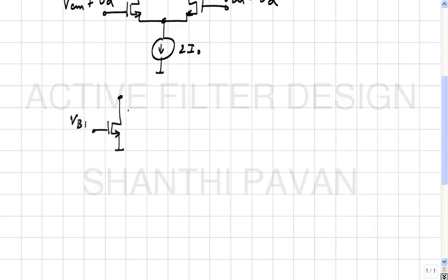This is the current source. This current is I in the sense that VB1 is chosen such that the drain current is I and VB1 is generated by a mirror and so on. And now we have a cascode where you not only have the lower device. What must this potential be? If I want to have the same current, what should the potential there be? It must be also VB1